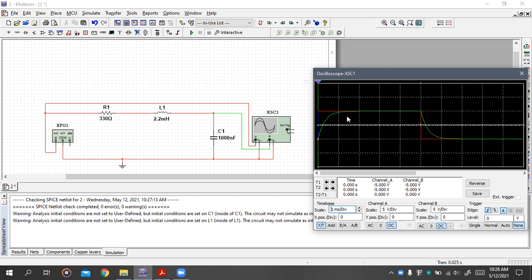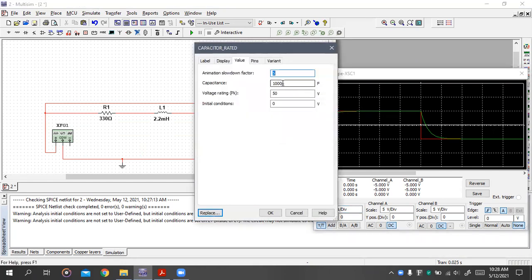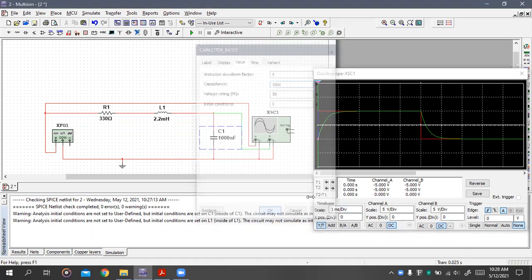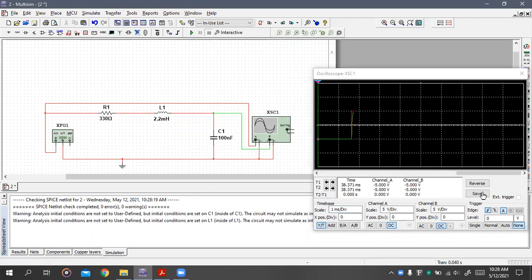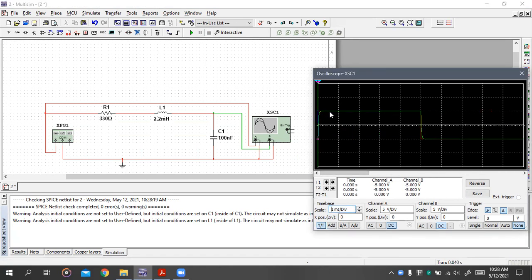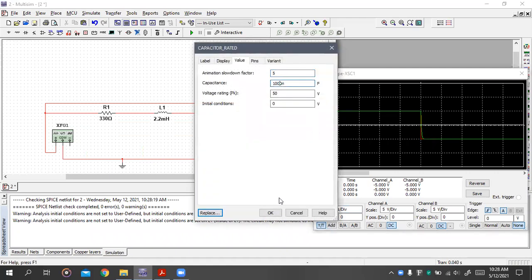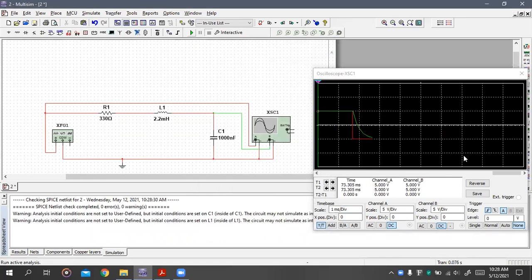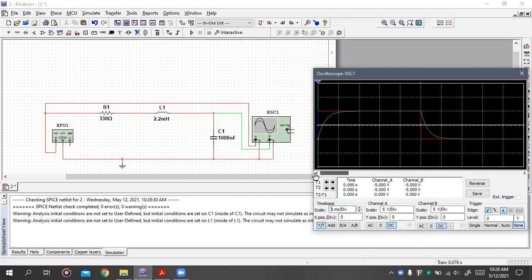So what I mean is this: we can get to the red line faster, but not bounce along it. So if you put 100, like earlier, see, it gets there, but it doesn't bounce here. This is what you call a critically damped response. If you put 1,000, it doesn't bounce, but it takes so long. It takes a very long time to get to the red line. So that's why you call it an overdamped response.